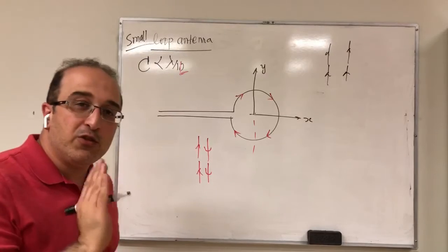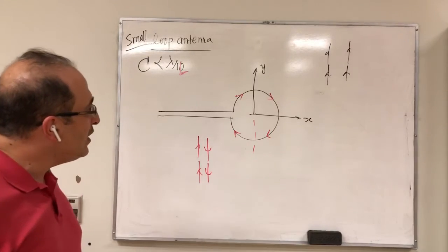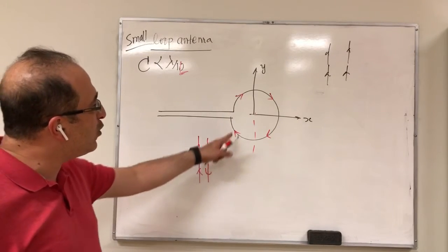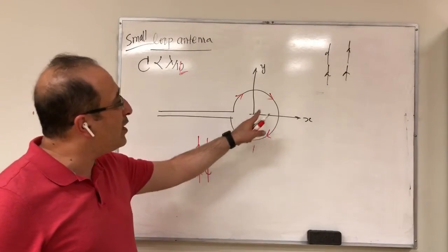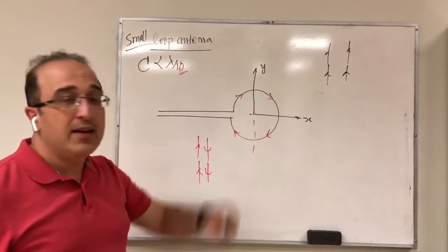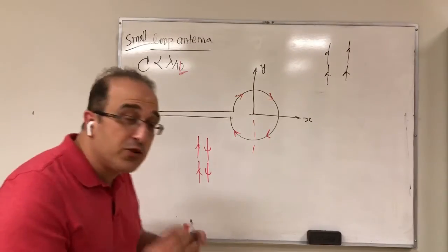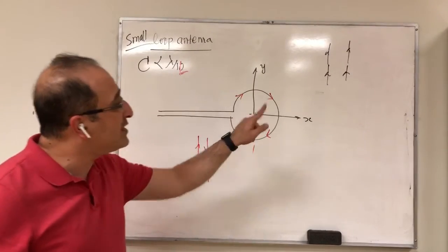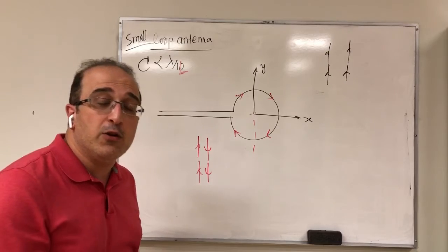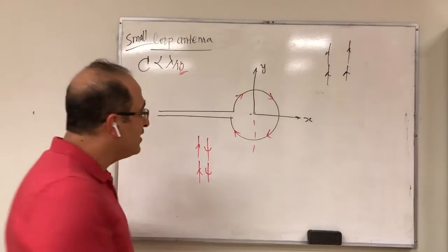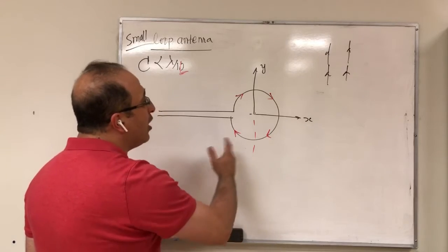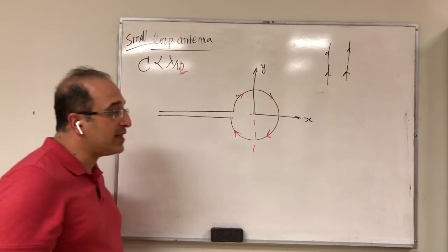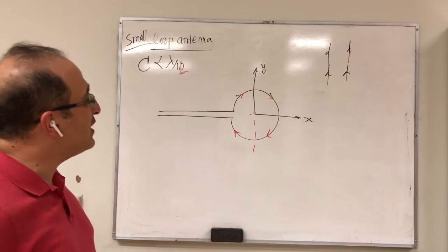So that's something to keep in mind. You get the result that in this direction it cannot radiate, which is true. A small loop has a null on the axis of the loop, in fact. So it is interesting that you get a null, compared to the circumference lambda, where you get maximum radiation.